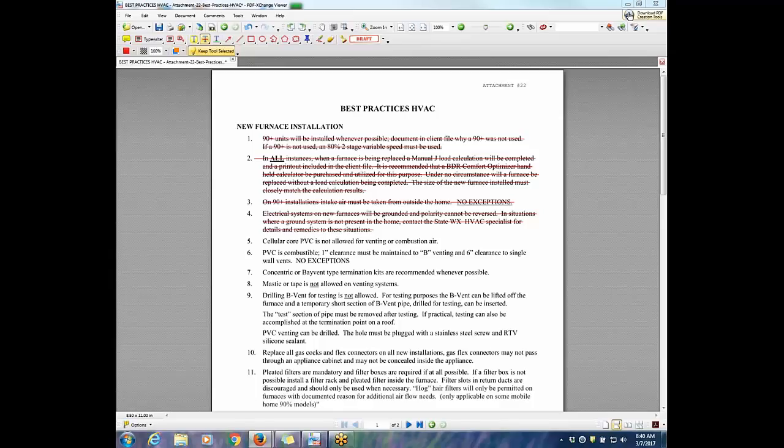Okay, so if it is a Schedule 40, it's going to be a solid core. Well, not necessarily. Schedule 40 doesn't mean solid core. Cellular core can be Schedule 40 too, but it's that additional marking of cellular core or pressure pipe. If it says pressure pipe, it's solid core. Again, anyone who's looked at it can tell the difference.